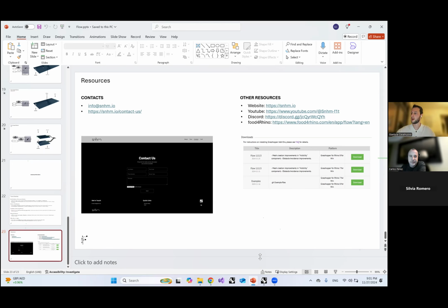Yes, so everything in Flow can be designed in Rhino or Grasshopper. So if you are able in Grasshopper to set up different boundaries, you are able also to populate different boundaries with different number of points. With, for example, populate geometry or populate boundary rectangle, you can just populate with points and choose different numbers of points. And then you can just use these as generating points for the agents. And you can even assign different speeds, different colors in order to differentiate them. But you can also use Rhino. So you can just input points in Rhino and reference them into Grasshopper, and then create the agents.